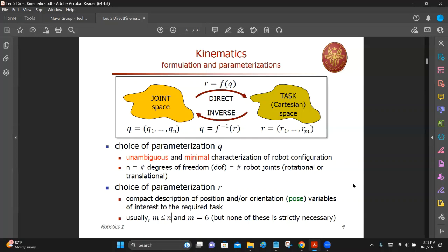Let's say you want to draw something on the wall using a robot manipulator. Okay, let's say it's on the table, not the wall. So you only need X and Y, right? And even Z you don't need. You can put the pen in whatever position touching the paper, and after that you don't need to control the height.